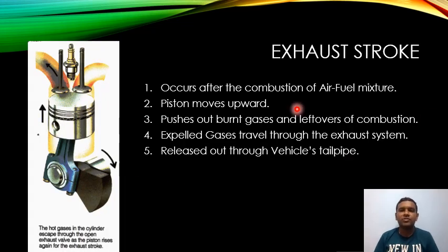This is the last stroke of the four-stroke petrol engine cycle. Of the four strokes, this is the fourth stroke, known as the exhaust stroke. This occurs after the combustion of the air-fuel mixture. Here the piston moves upward. The piston is primarily at the bottom dead center and moves upwards towards the top dead center. What we have to note here is that the intake valve is closed and the exhaust valve is open. And what happens during this stroke is that it pushes out the burnt gases and leftovers from